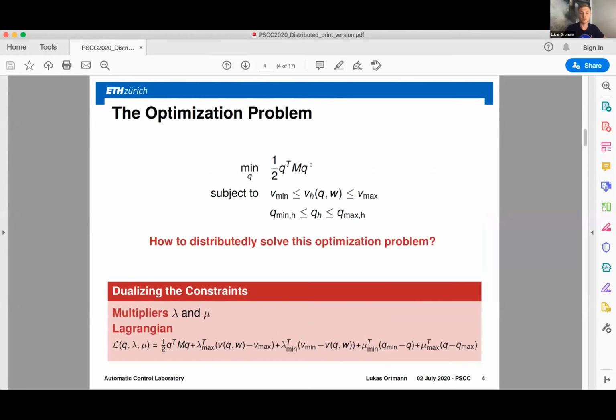And therefore, we are penalizing voltage violations. We could also do this with a 1 norm, where we are just going to sum up the different voltage violations in the Q points here. But then the derivative would be different. It would still be implementable, but if you go for the quadratic version, then you end up with these nicely distributed controllers.